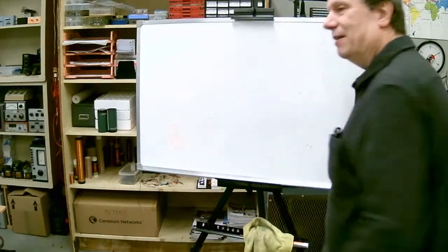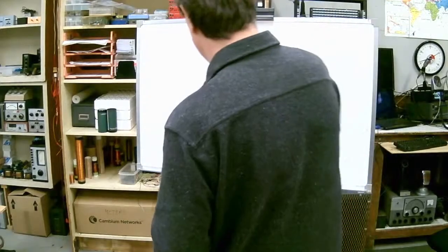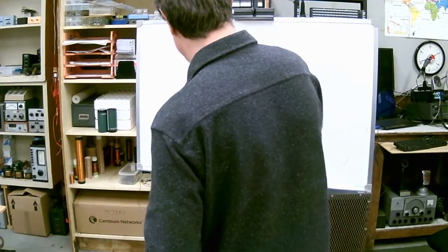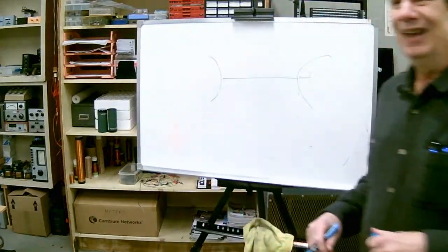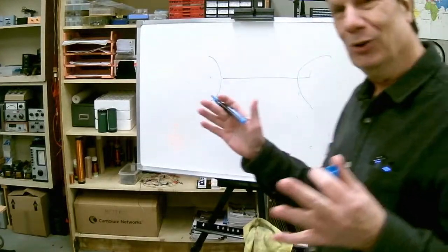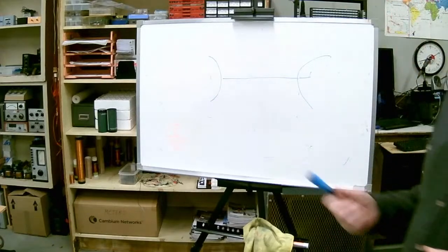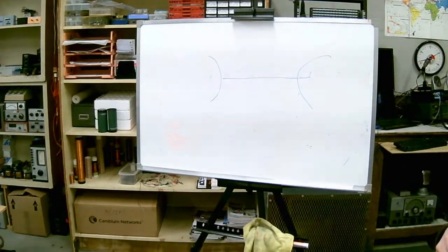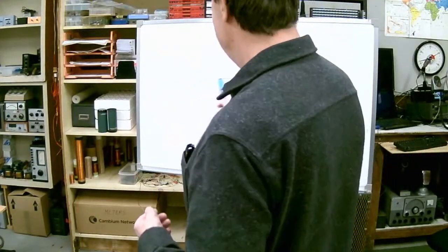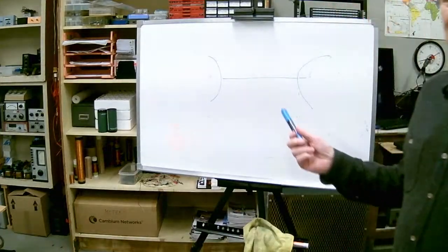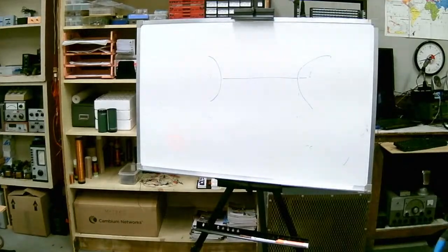Now there's a thing called a passive repeater. There used to be some up and down pipelines, where you just had basically a parabolic dish here, a piece of transmission line, and another parabolic dish here. It was just for getting over hills and stuff where it wasn't convenient. You don't have to power it. It's totally passive. And because of the reciprocity, we know it's going to work. Any signal coming in here is going to be absorbed by that, transmitted down the transmission line. There's a lot of loss in here. It's not a real efficient thing, but sometimes all you need to do is get over a hump someplace.